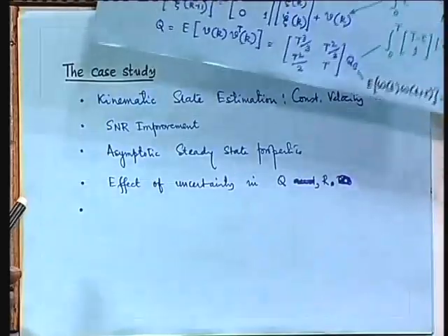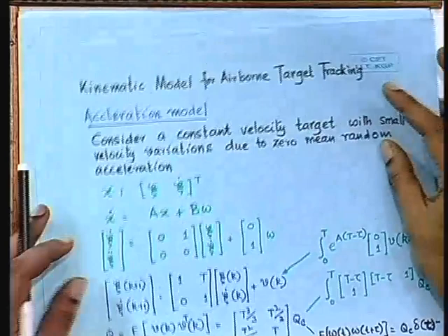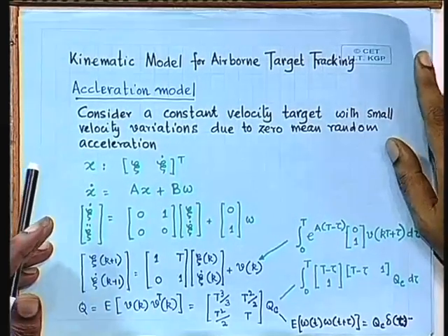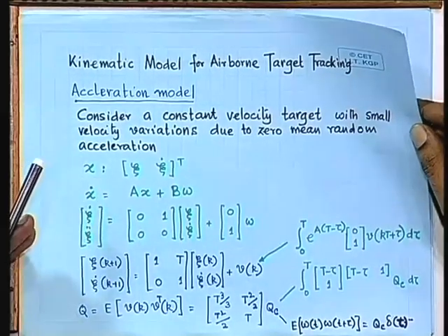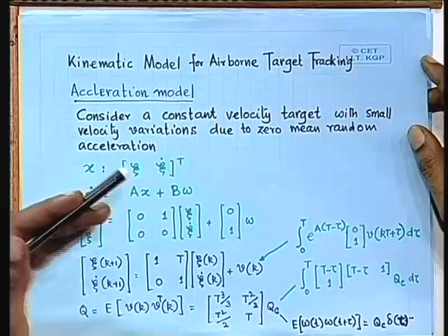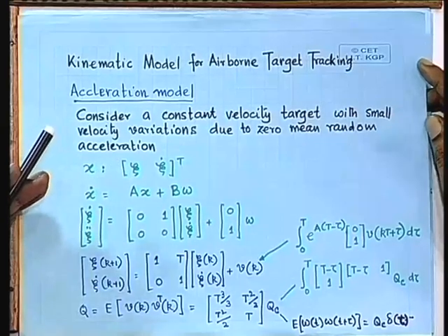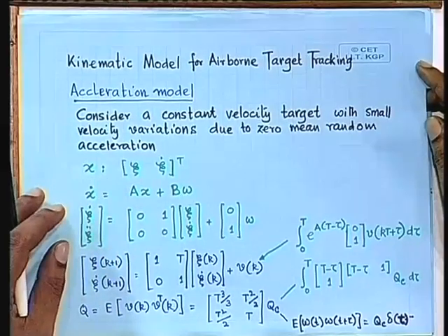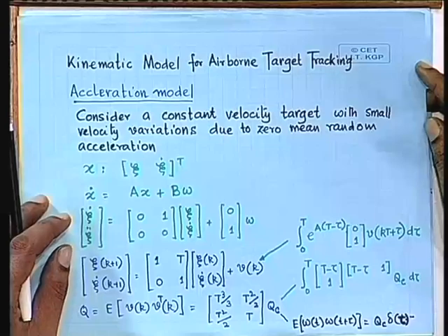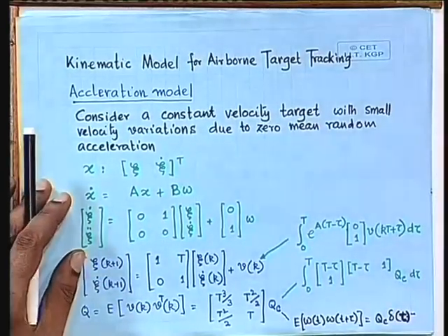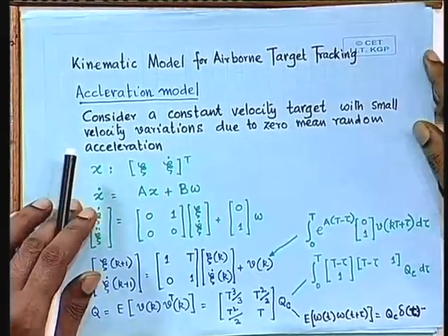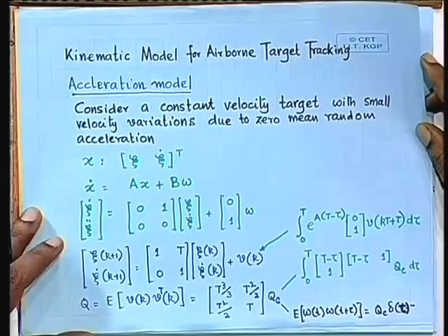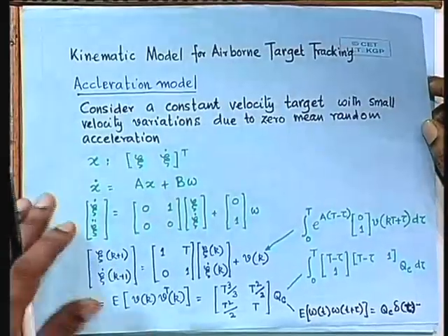Okay. So now this is sometimes called a second order model for obvious reasons, because the matrix has dimension 2. Sometimes it is called a constant velocity model, right, where you have a random acceleration input. Sometimes you can assume otherwise. You can assume that it is a constant acceleration model also, in which case your state dimension will become 3. Then you will assume that you have a small random jerk input. Jerk is the derivative of acceleration. People use such models also, especially for tracking various kinds of targets which may be suddenly trying to speed up, again slow down in a random fashion. Sometimes it is useful to use the jerk model or the constant acceleration model, I mean a 3-dimensional third order model.